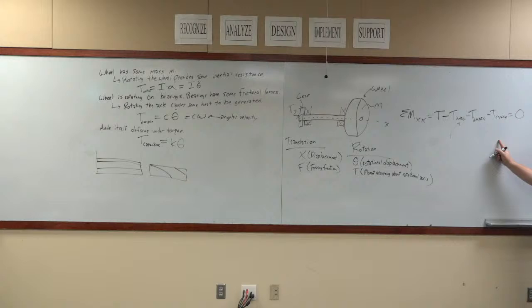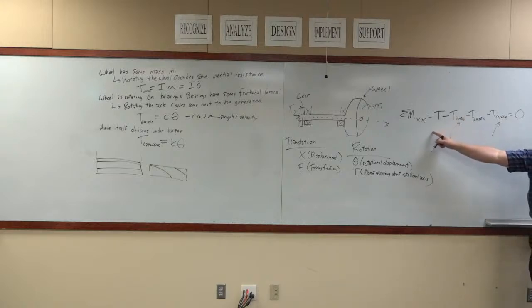At a constant speed, with a constant torque, this is also constant. And this ends up being 0 because you're not changing that spring value. You set something on a spring and you don't move it, that spring doesn't absorb anything. The spring has already reached its maximum loading when it's at equilibrium. This is also 0. At equilibrium, traveling at a constant speed, all of the torque you're putting into the system is going into heat.